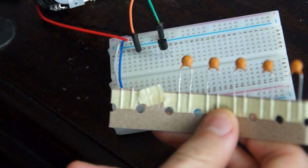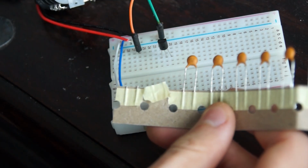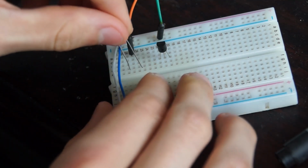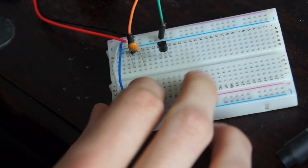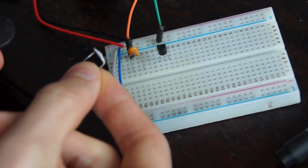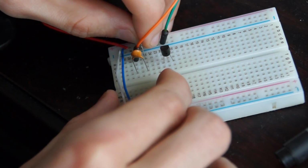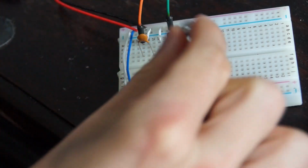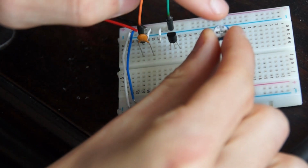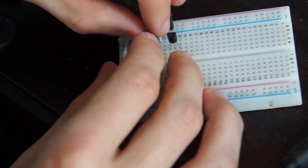Okay, now for the input capacitor, I'm going to use a tiny capacitor. This has about 52, that means it's about 5 nanofarads. So this input capacitor will go from our input to a new connection, and then here we're going to need a voltage divider. To set up the voltage divider, I'm going to connect the 2 rows next to it to negative and positive voltage. And then I'm going to use a 1 million ohms trim pot. 10.5 means 10 times 10 to the power 5 is 1 million. And that's going to be our voltage divider.